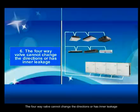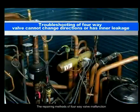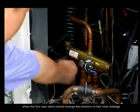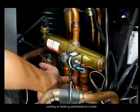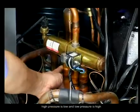The four-way valve cannot change direction or has inner leakage. The repairing methods of four-way valve malfunction. When the four-way valve cannot change direction or has inner leakage, the phenomenon is that there is no sound when changing the direction. Cooling or heating performance is bad. The middle pipe on the downside of the valve has higher temperature. High pressure is low and low pressure is high.